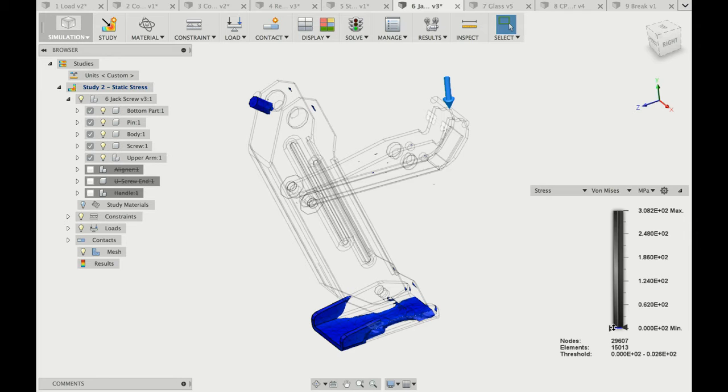And it's also kind of self-explanatory. If the force is going down through this pin and it freely rotates around this pin, this one doesn't carry much load. It's there to position it under the car and to better fit the space. However, it doesn't transfer any load, so it could be much tinier. So this is a type of directional guidance that the software gives me to make better design decisions.